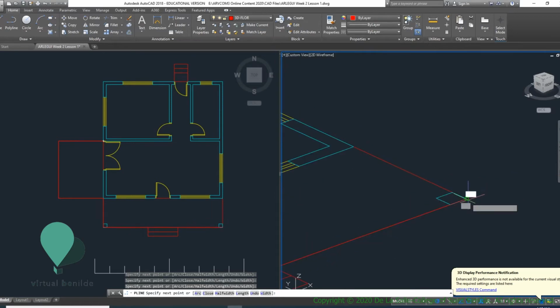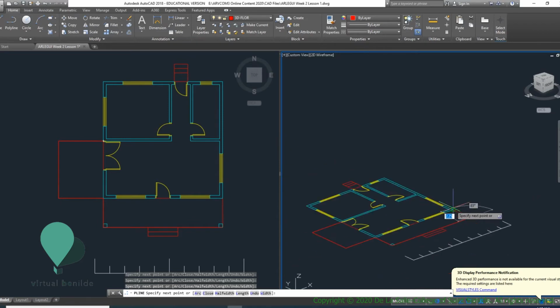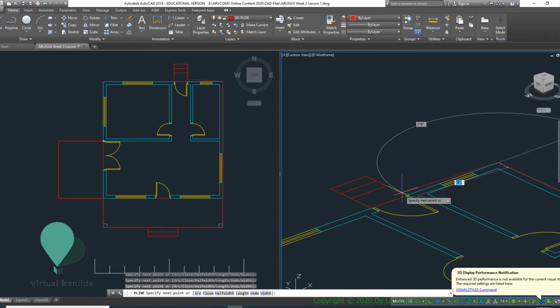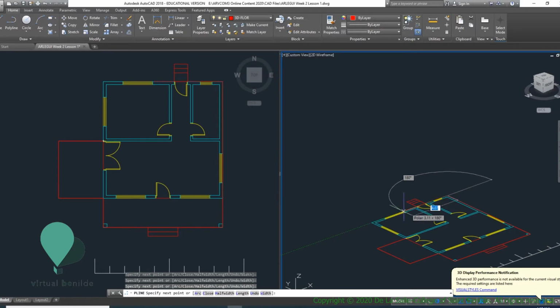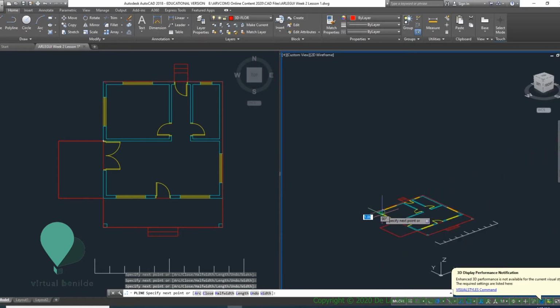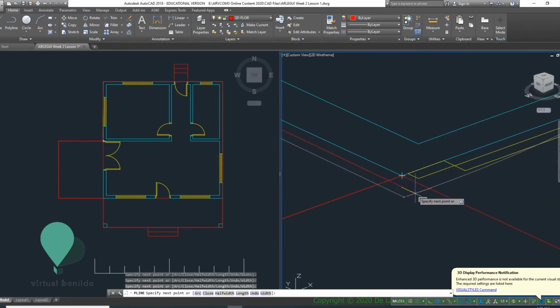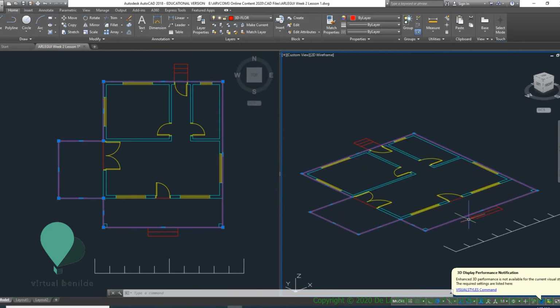I'm panning and zooming out with my wheel mouse. Press here to this corner. Of course, I knew that the white cross means that was where I began. So all I have to do is close this by pressing C, enter. You can see the polygon line construction.